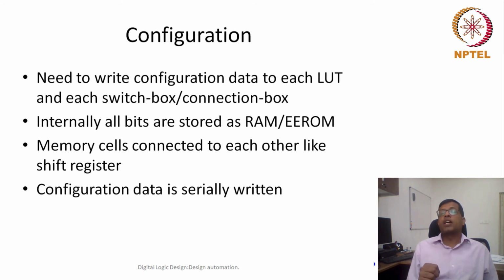From the external interface, let's say your configuration is in a flash drive, a USB drive, or your host computer, then using a USB interface or a serial-in interface, all of the bit data could be given one by one. Internally, during the configuration time, our whole FPGA logic works like a single shift register.